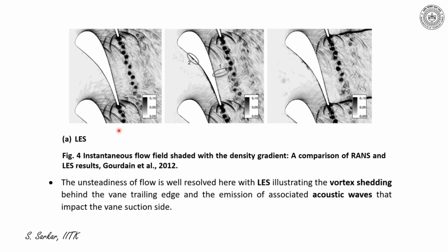When isocontours of density gradient are presented, it resolves the shading of vortices behind the blade, appearance of acoustic waves within the blade passage, apart from formation of shock on the suction surface. Some vortices appear on the pressure surface because of acoustic wave disturbances.